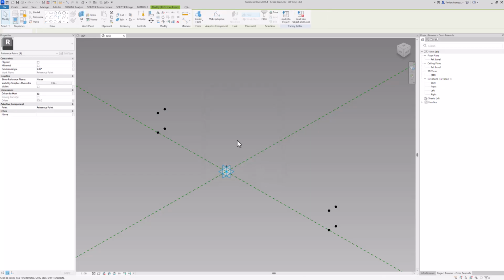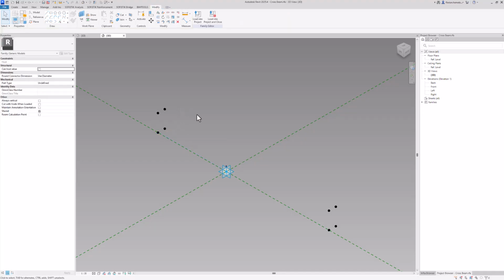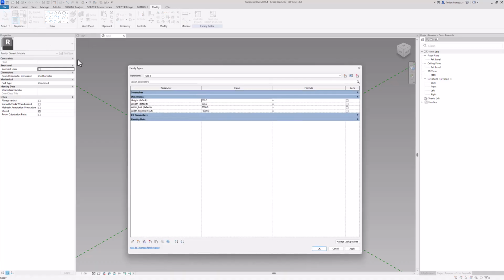Once more, here you now see that the coordinate system is sensitive to plus and minus. These points were created in reference to these origin points, meaning that the coordinate system of this point is relevant to the offset. I can simply come back to my height parameter and set it to negative.